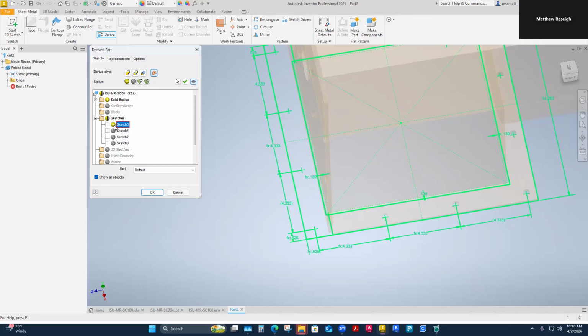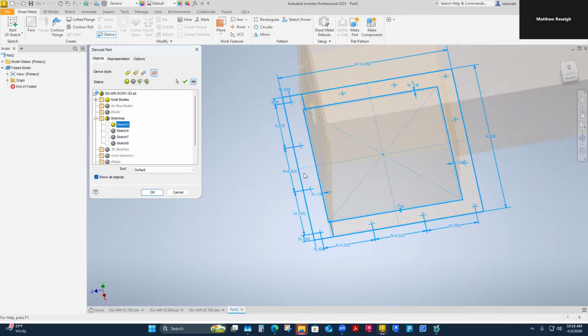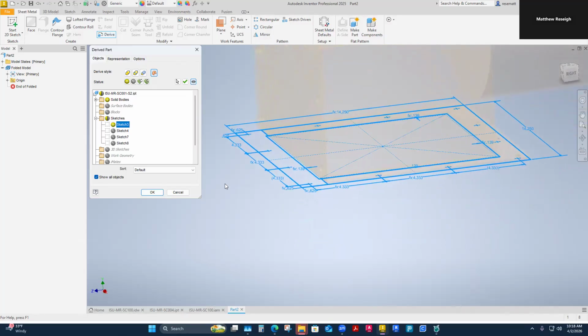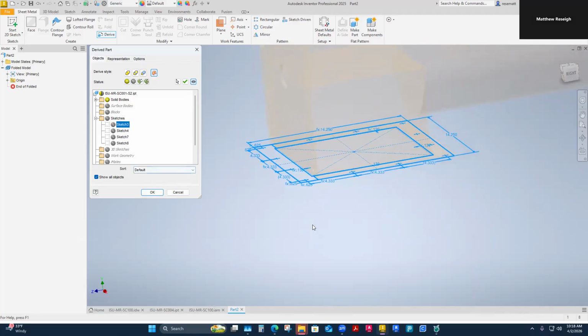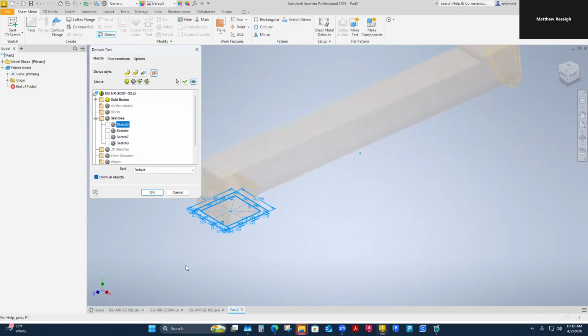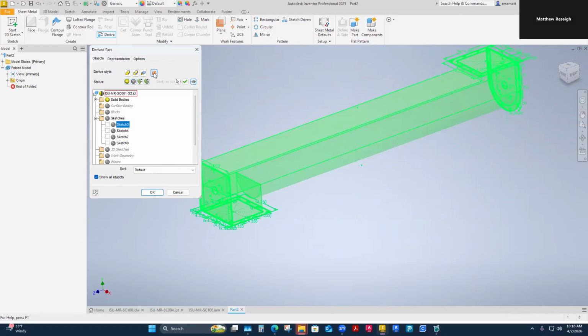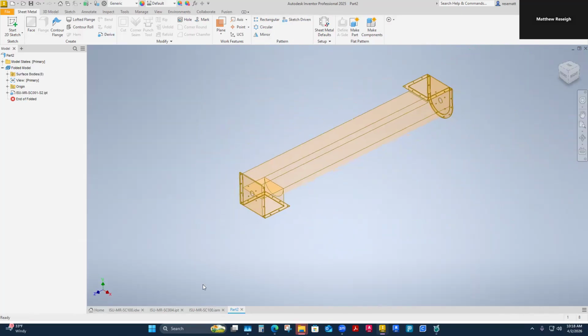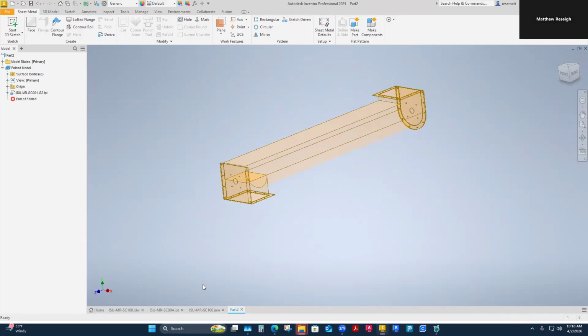But on the 1/4 inch part, I'm going to need these hole locations to add to my flange that I bend on here. I don't need them here because I'm not working with 1/4 inch. I'm thinking of working with the 3/16 because I think I can probably whip them out pretty fast. So all I really am bringing in is the bodies as a surface, just essentially how it looked the last time we used it.